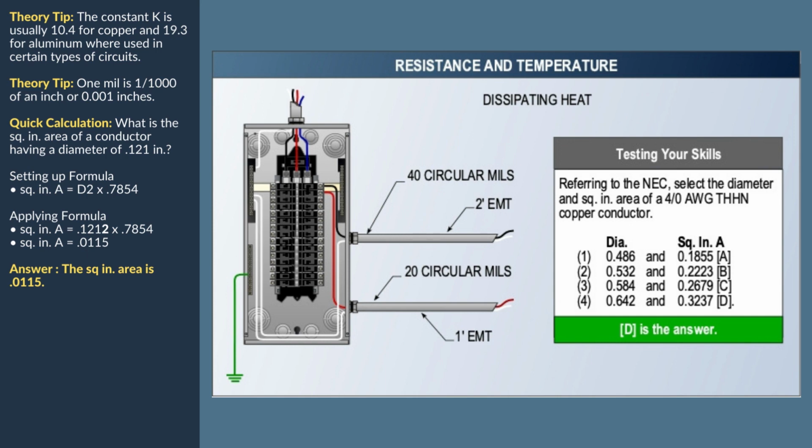The area of a circle in circular mils may be given as follows. A, which is the circular mil, equals 0.7854 d squared, divided by 0.7854, which equals d squared. The area of a circle in circular mils can be calculated by merely squaring the diameter.